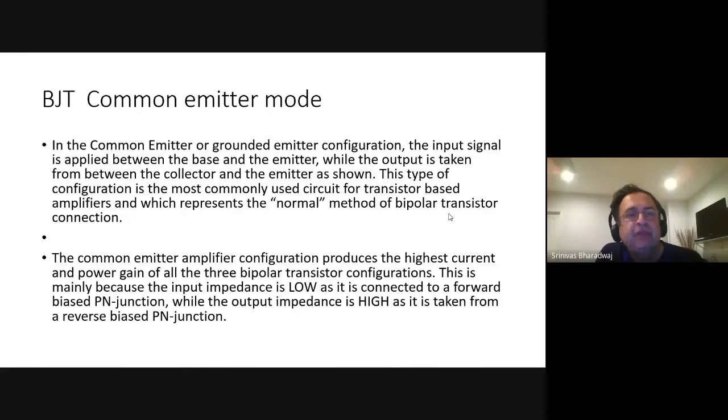That constant is the amplification. If delta VBE goes up so much, delta IC will go up by a linear multiple of it, at the operating voltage at which you bias the transistor. That's what they are saying in all this.